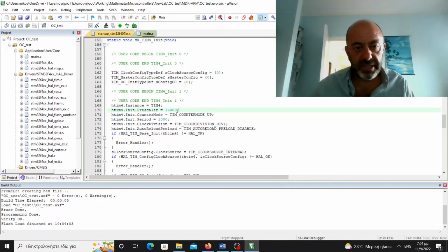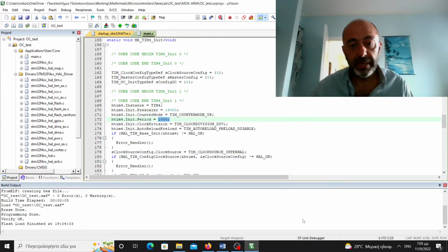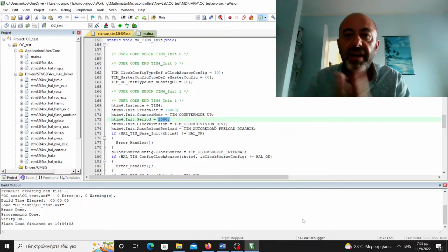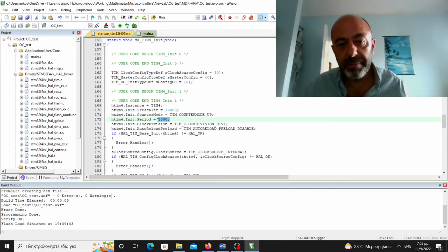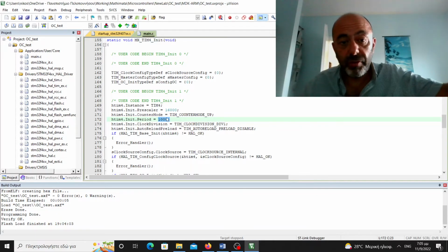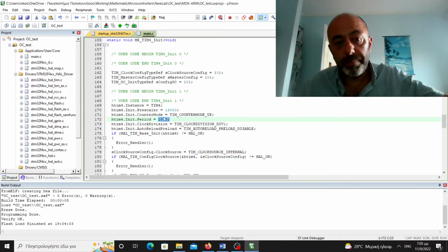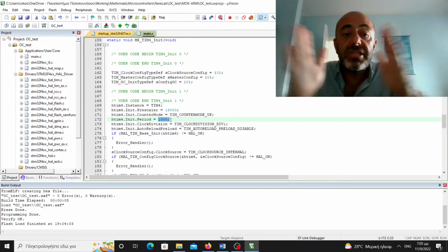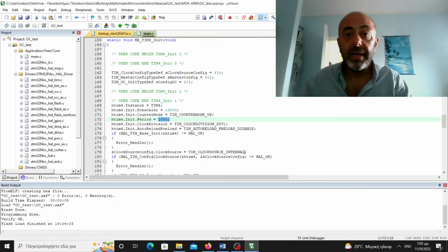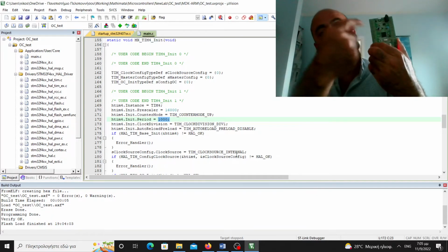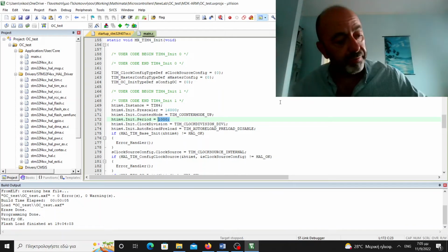You can see, for example, that the prescaler is at 16,000 that I selected. The period of the counter is 1000. So let's think about it. We defined that the first LED should be toggled at number 500, which is about half of the values of the timer we set. The other one to be toggled at 1000. This is the last value reached by the timer before it overflows. But what happens with the rest of the 2 pins that were set to toggle at 1500 and at 2000? These values are never reached by this timer. So this is the reason why we do not have anything happening on the other 2 LEDs, and only 2 LEDs can be seen turning on and off.